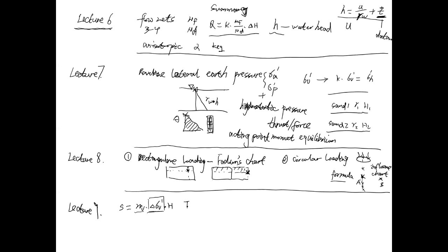The other important part is Tv equal to cv t divided by d squared. Tv is an important index, and it correlates with the coefficient of consolidation, the time and the sample height. This can generate lots of questions. Tv has a correlation with U, if you recall.